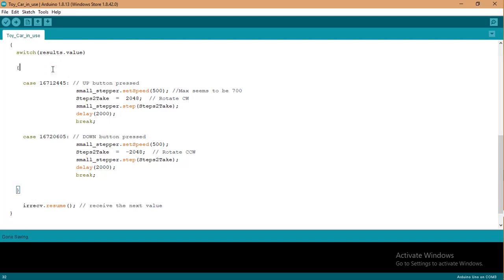But if I want it to blink, I will place it high, then have a delay, then place it low. So it's high, delay, so it's staying high during that period. Then it executes the next command, which is low, then delay, so it's staying low for the period that's being delayed. So that's basically the delay.